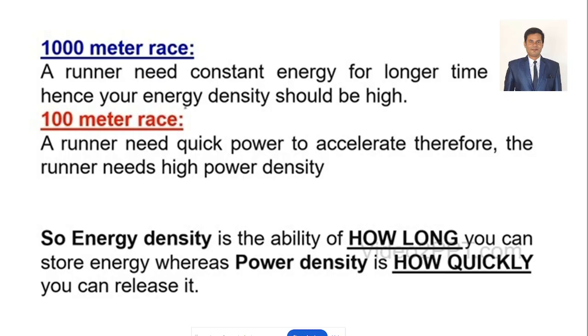How much amount of charge, amount of current, are you dealing with for a specific hour? 2 hours, 50 amperes. 1 hour, 25 amperes. Like 3 hours, 75 amperes. Correct. That is how the batteries are rated with ampere hours: how long it will give the current to the loads. We require the constant energy for a longer duration.